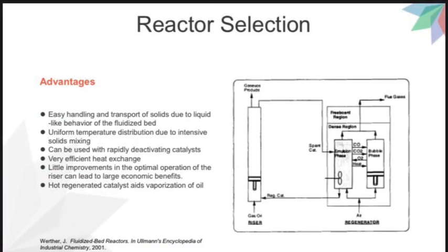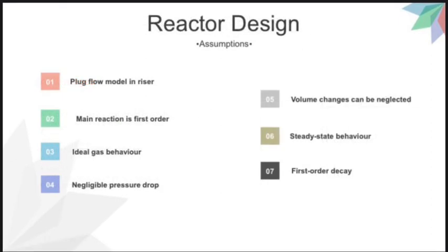The main advantage of this reactor is the efficiency of heat exchange. Hot regenerated catalyst will aid the vaporization of feed gas oil, while the heat produced during regeneration of catalyst will be supplied to the endothermic cracking process in the riser.